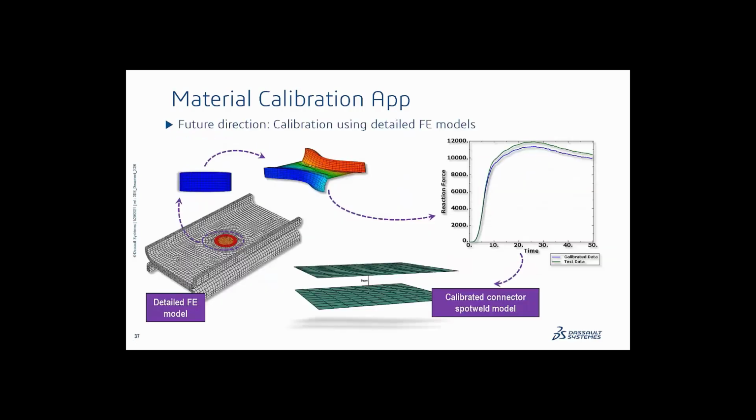So here's one example where we're modeling a spot weld, which we can do in 3D and be reasonably accurate, modeling this spot weld in 3D, and failure of that. But for system level models, you oftentimes want a simplified representation. So I want to represent this complicated spot weld and all the glory of its physics with a beam representation or a connector, if you will.